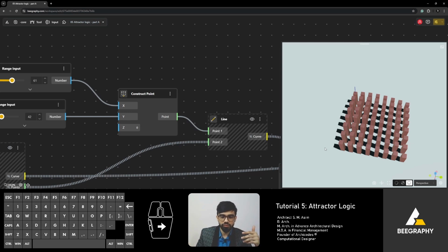And this is useful when you are stating certain logic, such as you are creating a facade and the shape of the facade should respond to the sun path or the incident radiation on the building. So you can do some solar analysis, do some simulations, and then on the surface you get different data points where too much sun is falling and where very little is falling in.